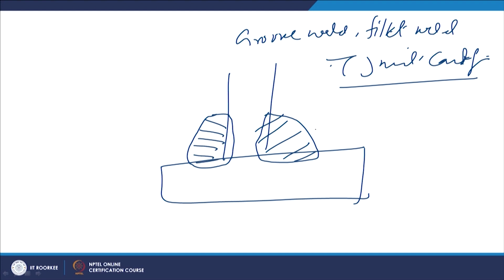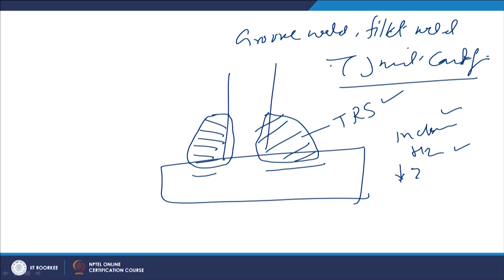Due to the shrinkage, with the tensile residual stresses, the metal next to the weld zone is under very restrained conditions, and if there are inclusions as well as hydrogen, high tensile residual stresses, and limited Z direction ductility, it will easily promote cracks or lamellar tearing in the region next to the weld metal, and this kind of crack will subsequently propagate into the base metal.